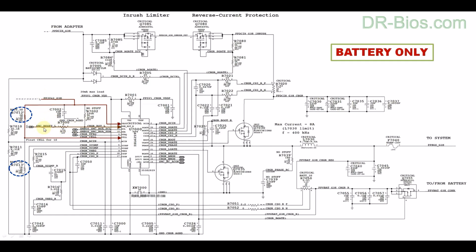PP3V42_G3H voltage and SMC_reset_L signal are generated in a specific process, and they enter charging IC. And at this moment, IC is waiting to hear good news from adapter. Then it realizes there is no news, so it remains in the state of waiting until adapter gets plugged in. But as PP3V42_G3H voltage has been divided, voltage division, it has entered charging IC exactly like when adapter was plugged in, which I talked about before.